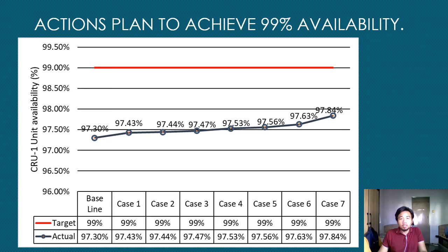Quality and control check on the new purchasing equipment is a crucial stage in improving the availability of the part. The new receiving part must be in impeccable condition so that the mean time to repair can be reduced. Other than improving the mean time for both operations of the machine, it is advisable to increase the number of equipment for each critical component so that the availability of the component will be higher. Increasing the number of equipment in the system will also improve the line configuration of the system to be more in a parallel line and reduce the probability of failure.